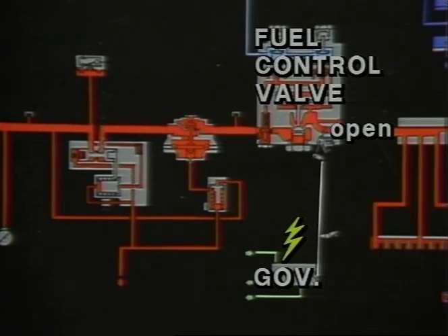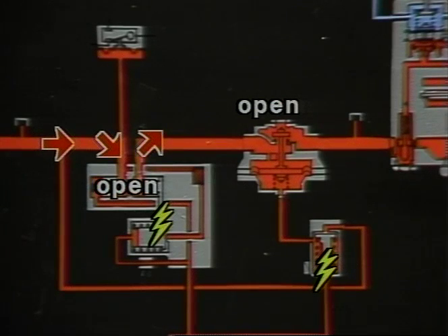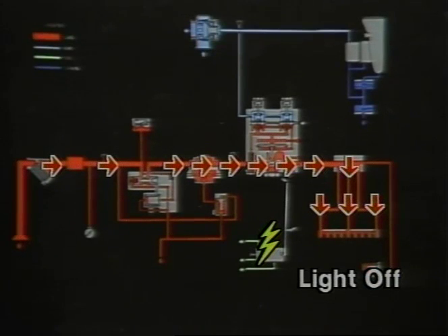10 seconds after turbine reaches 13% speed, the primary and secondary pilot solenoid valves energize and pilot gases open the primary fuel valve and maintain the secondary fuel valve in its normally open position. At the same moment that the fuel valves are opened, ignition occurs. 25 seconds after fuel and ignition, the torch igniter is turned off.